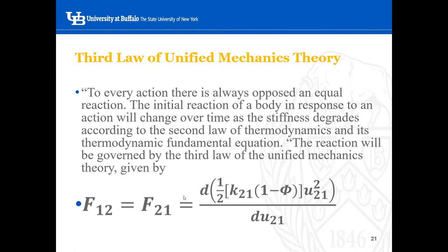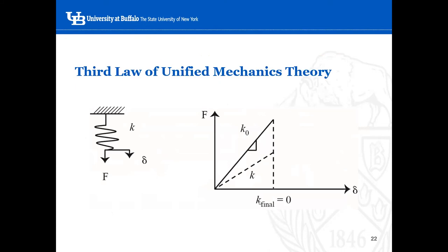So this reaction is the first derivative of the energy, but however, here K will degrade over time. And then displacement will get bigger. If you have a spring, for example, if you load it, unload it a thousand times, the stiffness will degrade and finally it will fail. It will break in two. That is what fatigue is.